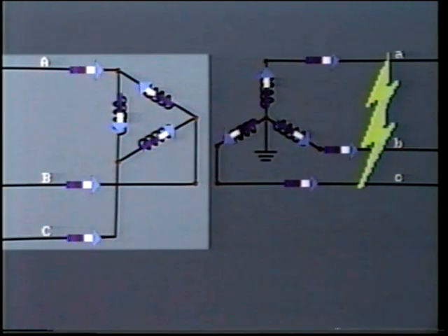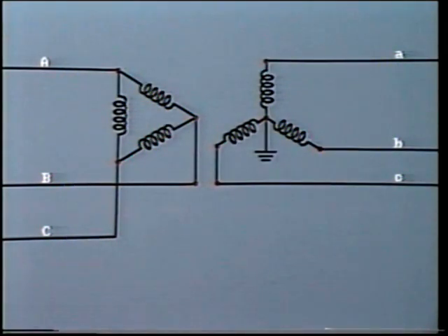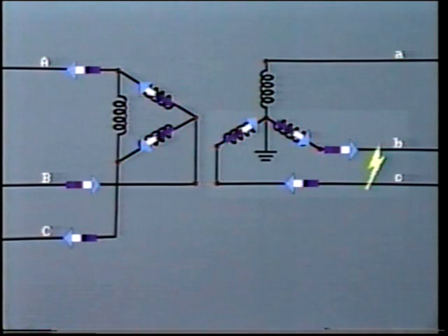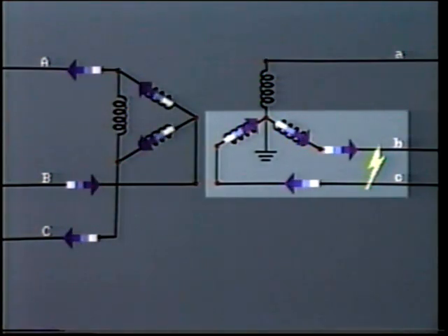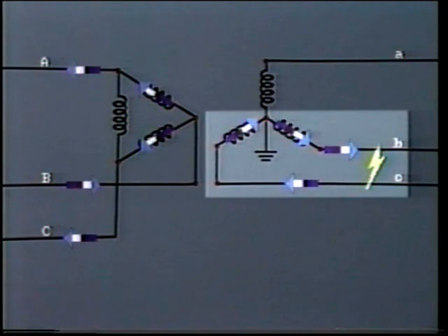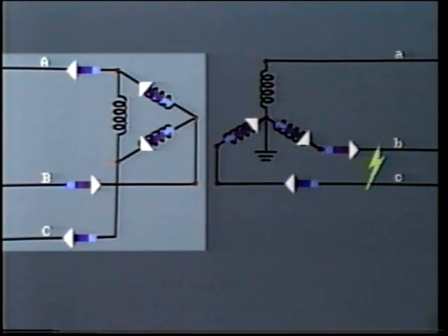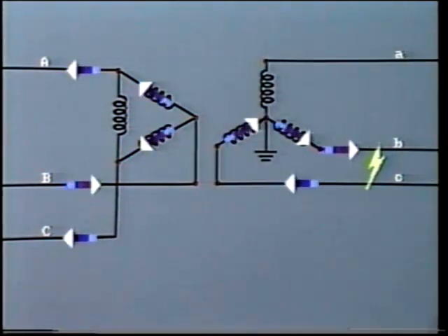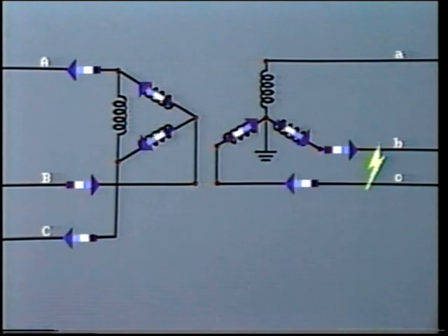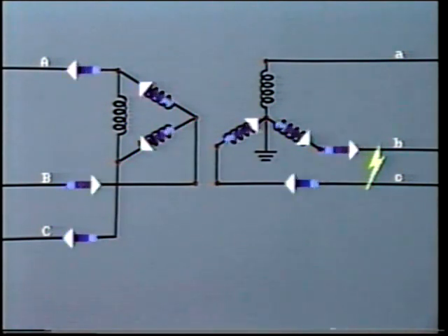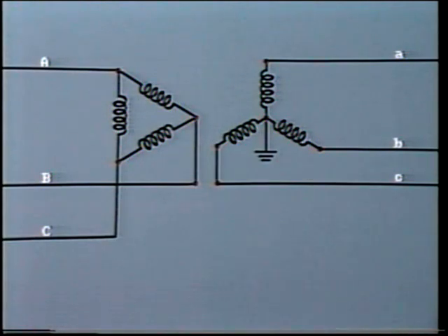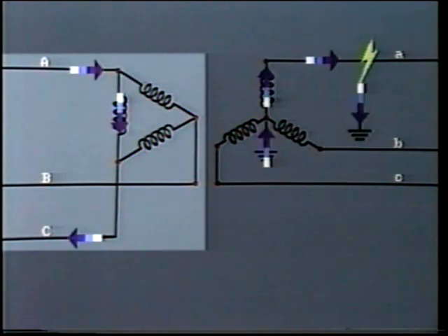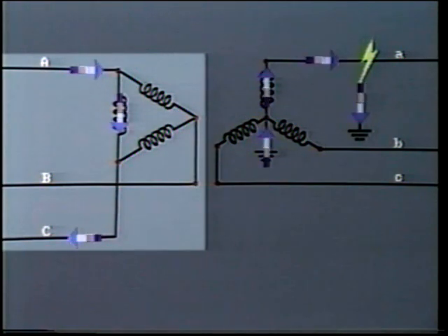the primary winding. In the case of a phase-to-phase fault on the secondary, in this example between lines B and C, then heavy fault current will circulate in the secondary B and C phase windings, and likewise, heavy current will flow through the associated windings on the primary. And this will be in addition to phase A load current, which is still being supplied. Where there is a ground fault, in this case on line A, additional current must flow through the associated phase on the primary, like this.